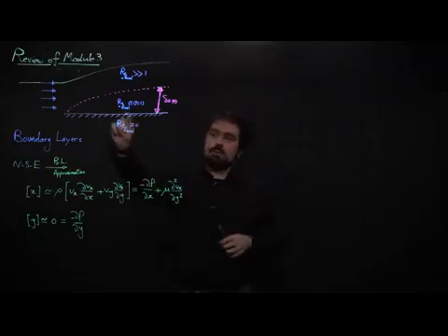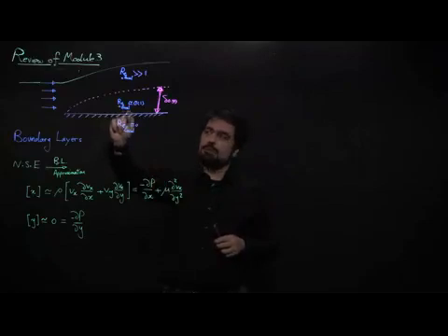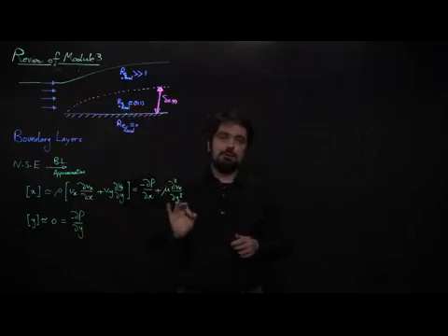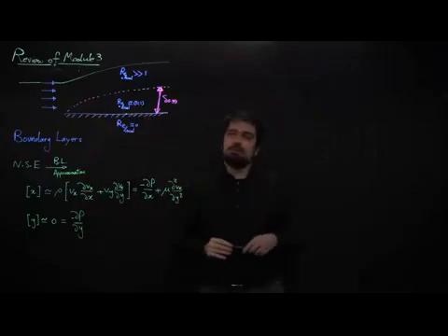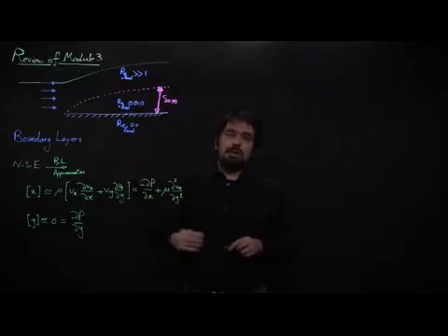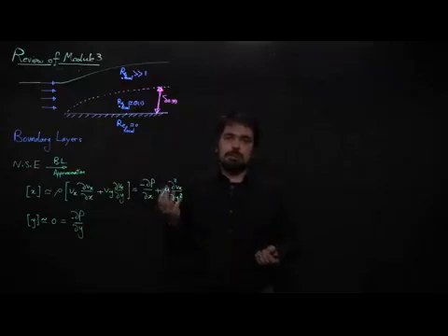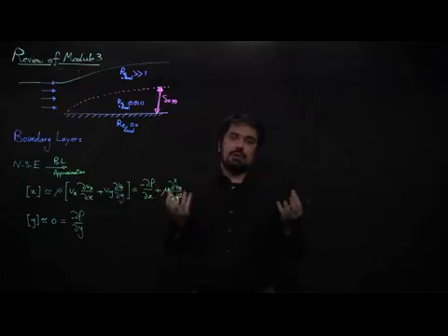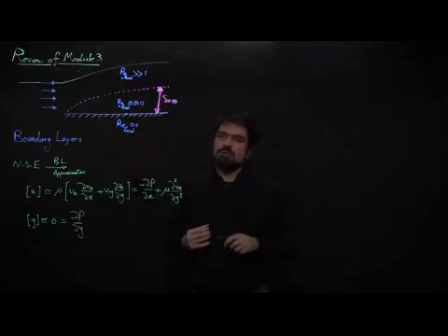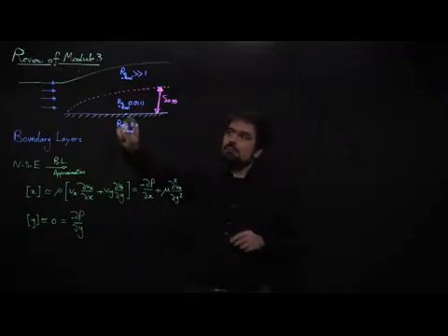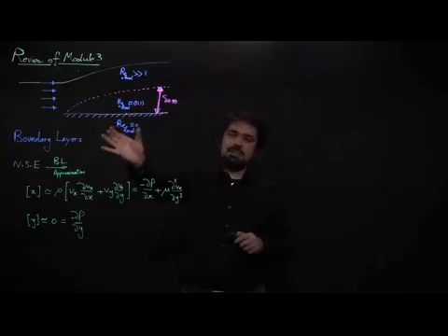A little bit above it, they also have a velocity that is non-zero and finite, but very small. So you can think of a region very, very close to this wall where fluid elements are almost stationary, having extremely small velocities. If you calculate a local Reynolds number there, and you can think of Reynolds number as a ratio of local inertia of fluid elements over the local viscous stresses that they feel, for those fluid elements it's almost 0.